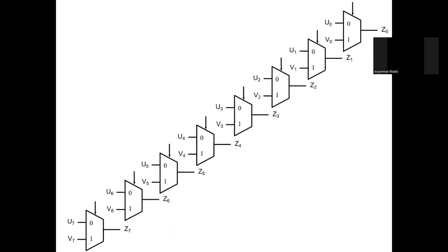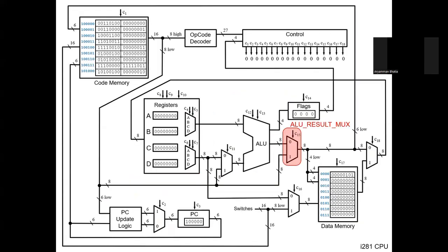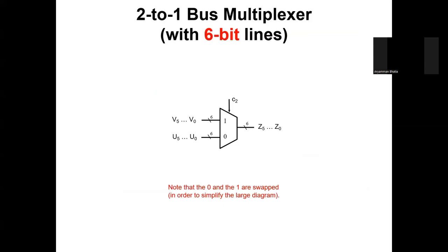And we get into how these multiplexers are choosing 8 bits, so how they're actually doing that. So yeah, we just take the inputs of each bit individually and pass the same control line to it. Yeah, and that's true for each of these multiplexers.